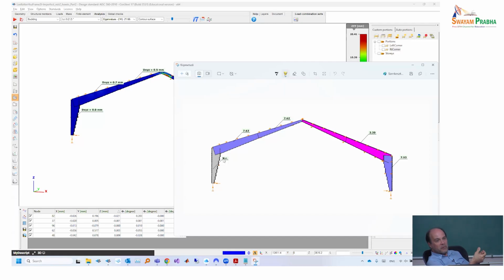Anyway, you as an engineer can always say that for some elements you don't perform a buckling verification because by feel you say it's not relevant. It's basically our decision. We typically try to calculate the critical members. Which one is critical? It's based on experience, feeling of the person. So here there is a certain indication that from load combination 3 point of view, this is not relevant. Load combination 3 is not relevant.